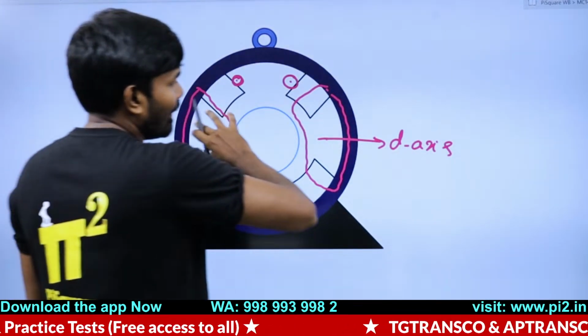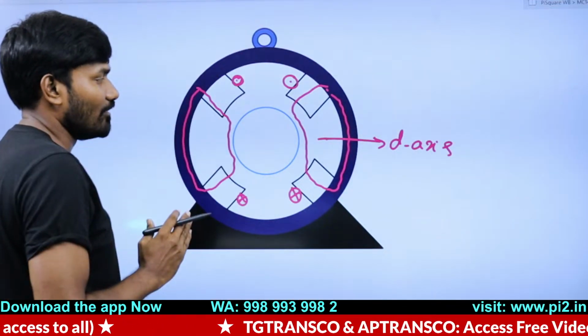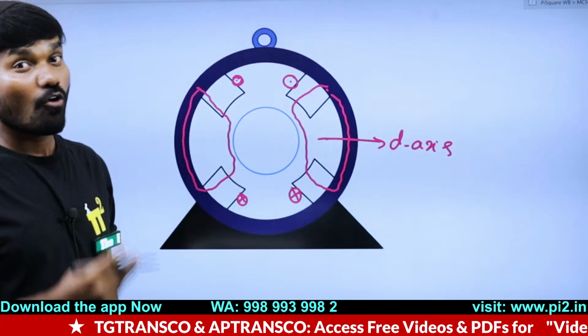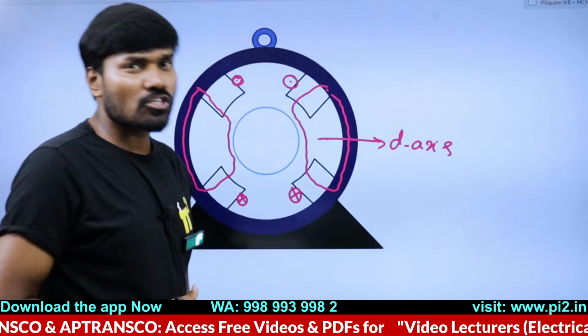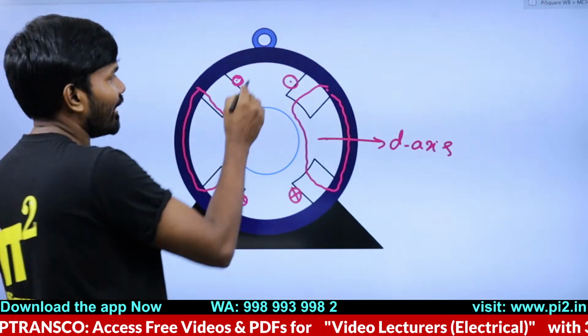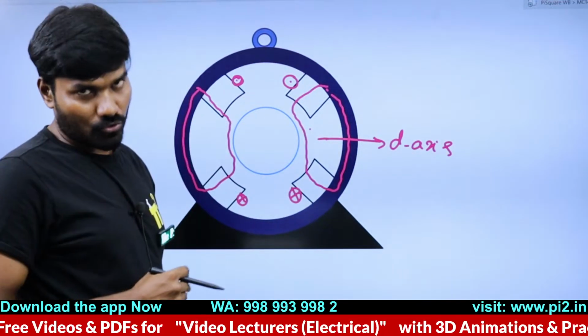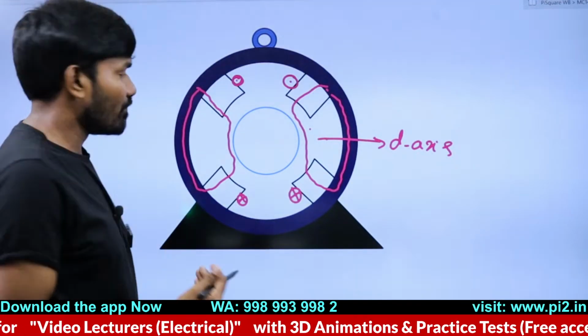This is the direct axis and this will be the quadrature axis. So two poles are formed. But how many pole projections? 4 pole projections. Now how many interpoles will be there? Definitely every interpolar region will have an interpole. 4 interpoles.